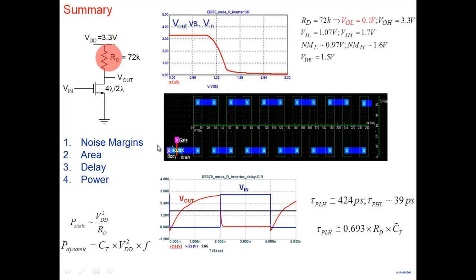Anything do you lose? And as I said, we will adjust the value of RD for that larger size to maintain 1.5 or so. So we'll not let the noise margin get affected. So of course RD becomes lower, so we'll end up getting this static power dissipation. But if RD becomes smaller, well, will this decrease or increase?